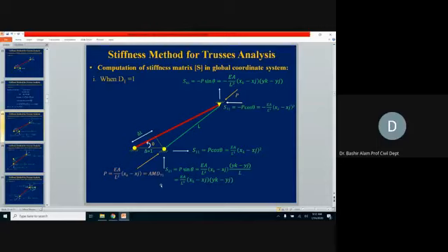Now we'll have a discussion on this first column. Maybe you cannot remember this now, but you need to find the analogy in this case. The member force produced will always be with the EA over L square, and times the coordinates corresponding to the direction of the displacement. Displacement was in the x direction, so x coordinates are involved now, and it is with the power 1.